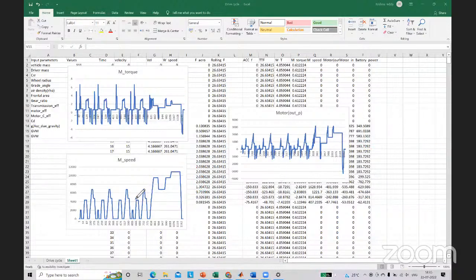And this is about motor torque: continuous torque, nominal torque, and the peak torques. And the speed, from these you can see the max is somewhat like 10,000 rpm, where continuously it is somewhat 5,000 to 6,000. Again, the base speed is going to be different, it depends.